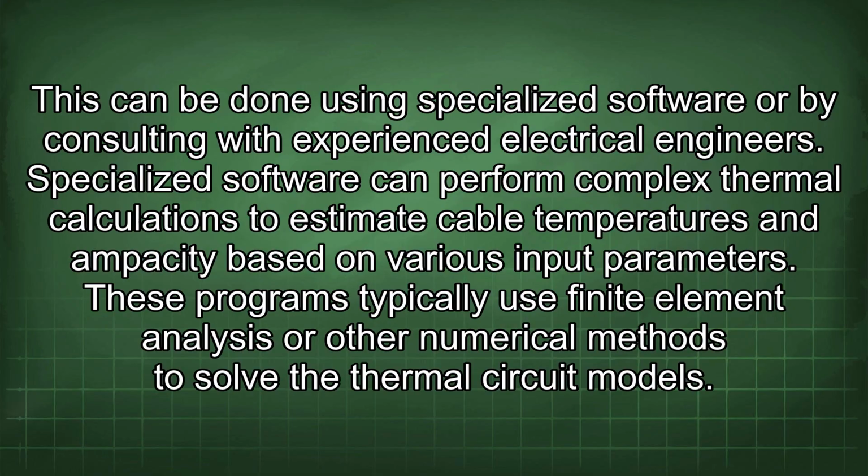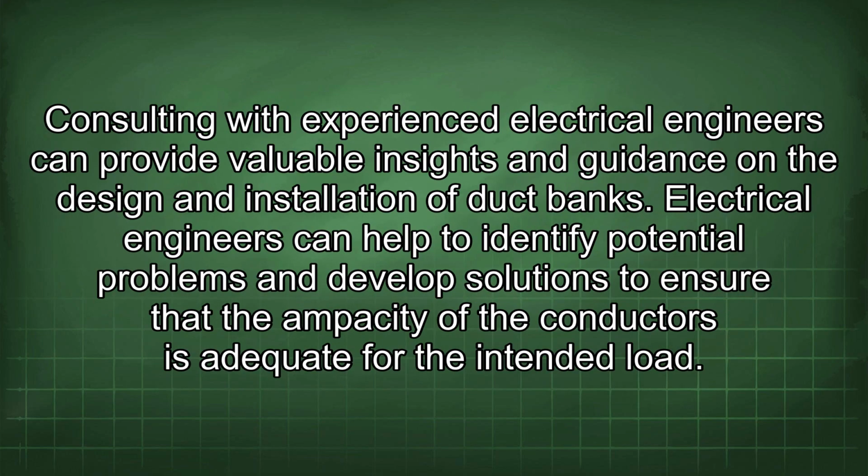This can be done using specialized software or by consulting with experienced electrical engineers. Specialized software can perform complex thermal calculations to estimate cable temperatures and ampacity based on various input parameters. These programs typically use finite element analysis or other numerical methods to solve the thermal circuit models. Consulting with experienced electrical engineers can provide valuable insights and guidance on the design and installation of duct banks. The electrical engineers can help to identify potential problems and develop solutions to ensure that the ampacity of the conductors is adequate for the intended load.